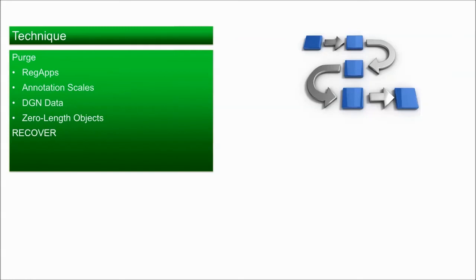AutoCAD actually has, and I don't have it listed here, a command called recover all, if you like to type in AutoCAD. It will recover the current file and any files that are XREF to it.